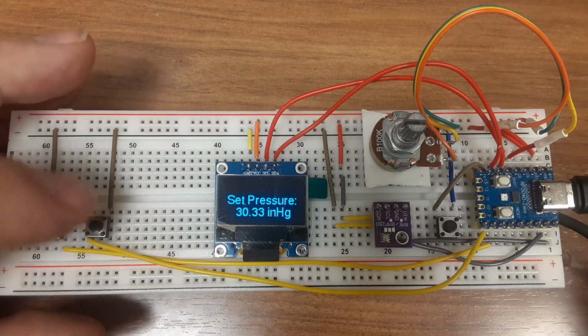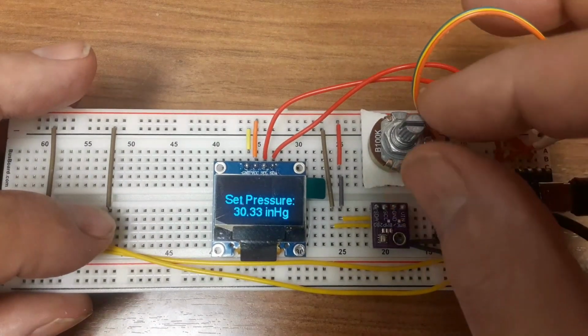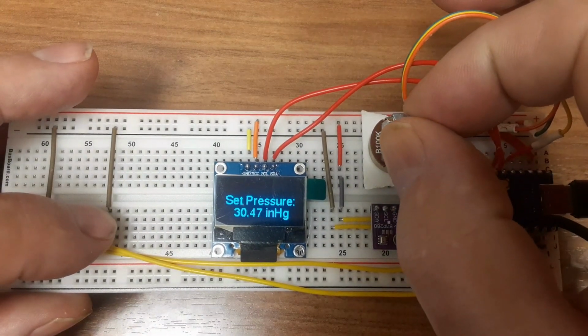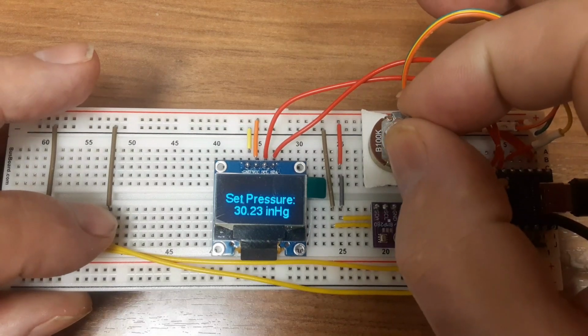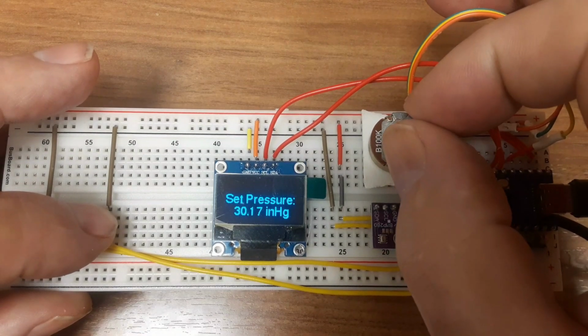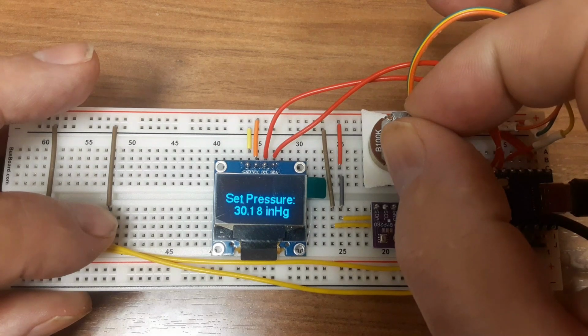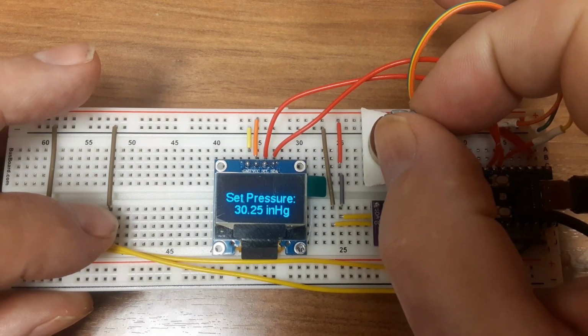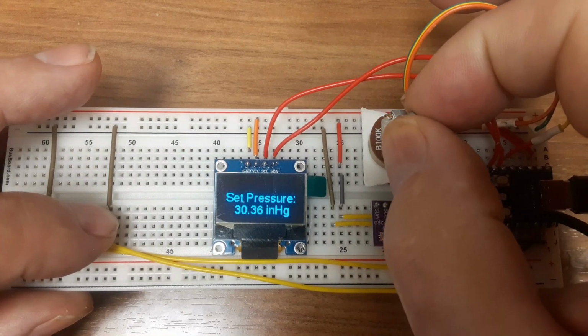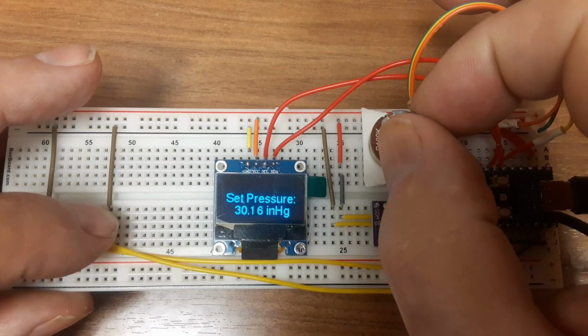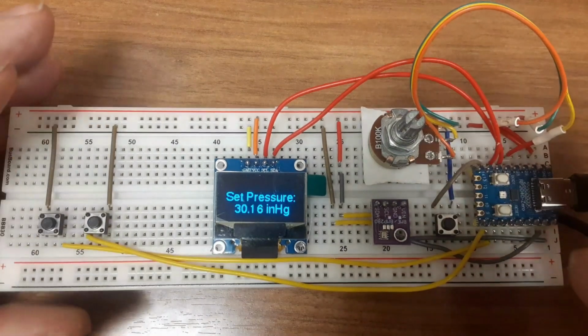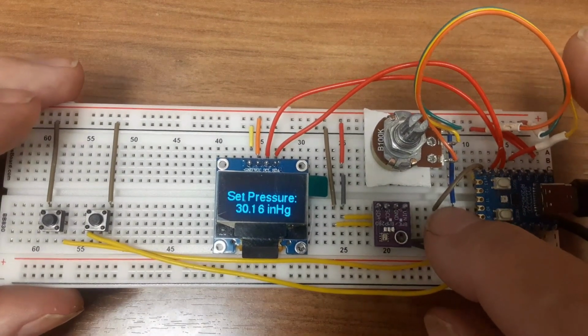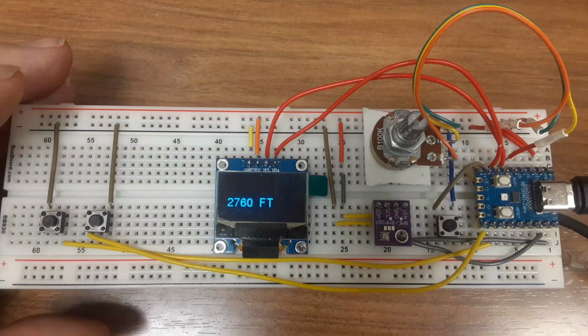And now I'm going to push the small digit control, and I'm going to adjust it for a reading of 16. There's 20, there's 16, 17, 18. It's very sensitive. Let's see what I can do here. There's 18, there's 16. And then I'm going to go back to the altimeter setting. And now we're at 2760. So now this is our true altitude at this location.